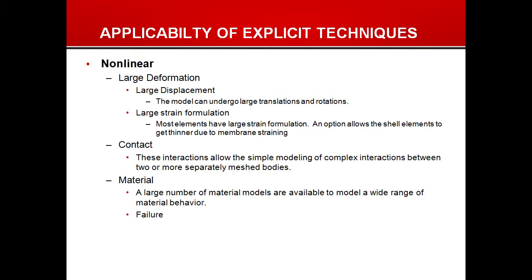Contact allows us to have interactions between various parts of the structure, whether you have different components or a single part that's going to fold back on itself. We can deal with that very, very simply using the contact creation. And then the final nonlinearity we'll talk about is material nonlinearities.